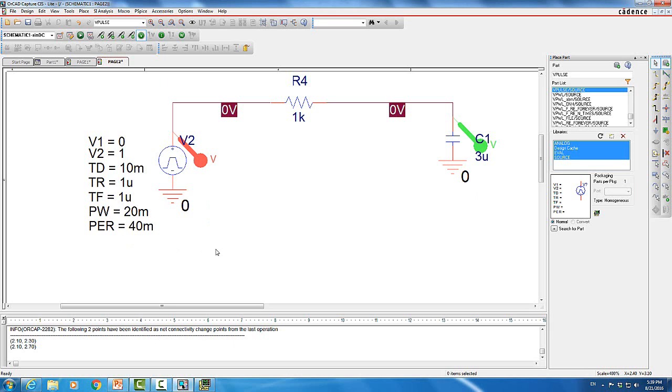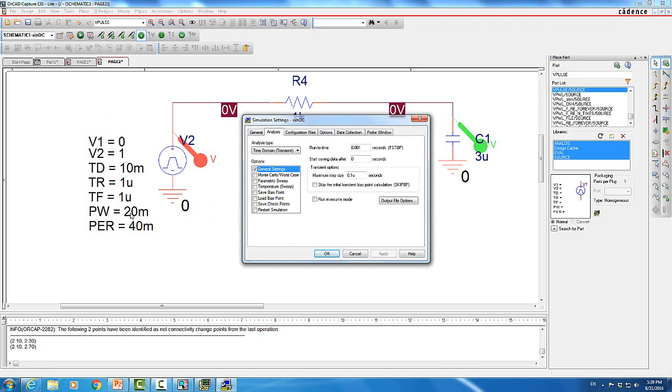So we're gonna define new parameters for the transient analysis. Now again, this is also a transient analysis response, so you want to plot things as a function of time. So the end time here, we're gonna make it 120 milliseconds, basically taking 3 times that rectangular pulse, and the maximum resolution, we're going to make it 1 micro.